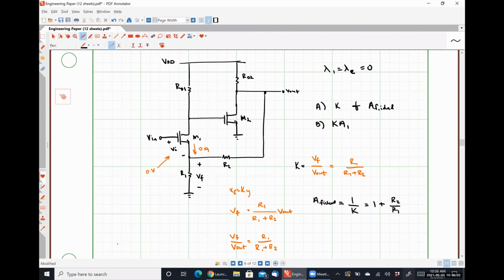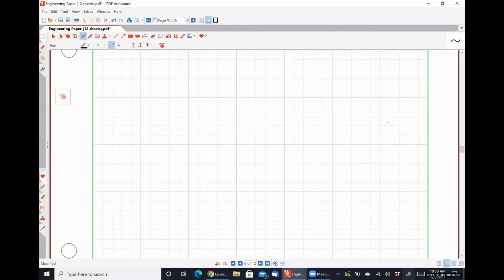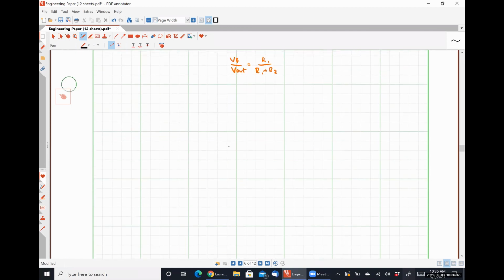Now, let's talk about figuring out what the loop gain is. This is where I'm a little bit more confident. Okay, so to find KA1, we set Vs equal to 0 and break our feedback loop. And I am going to break the loop at the place where I found the math to be the easiest.